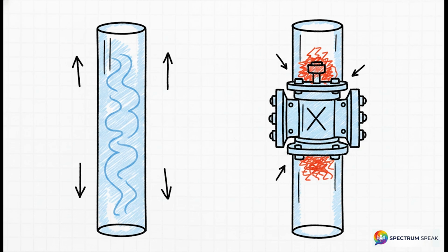Let's use a vivid visual analogy to make this concrete. Think of ground impedance exactly like a water pipe. At low frequencies, your ground path acts like a wide, clear, totally open water pipe. The water, or the current in this case, just flows easily. But at high frequencies, parasitic inductance kicks in. It acts like a stiff, heavy valve suddenly slamming shut, choking off the flow. Even a perfectly straight piece of wire becomes a massive roadblock for high-frequency current.